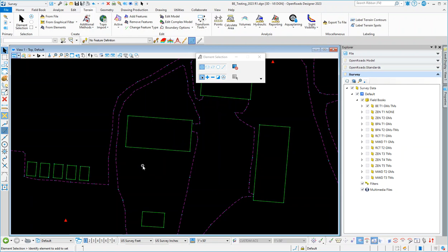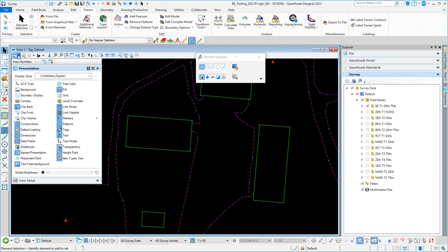One other thing that I've just recently found, which again just adds more inconsistency, is under the view attributes. I've been going round and round trying to solve this. There's a setting here called clip back, and clip back does have an impact on these manipulators.